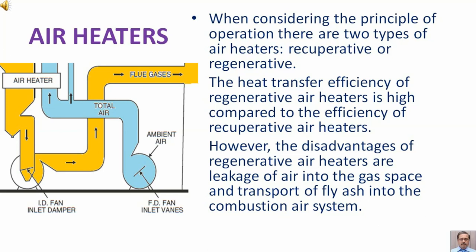The heat transfer efficiency of regenerative air heaters is high compared to the efficiency of recuperative air heaters. However, the disadvantages of regenerative air heaters are leakage of air into the gas space and transport of fly ash into the combustion air system.